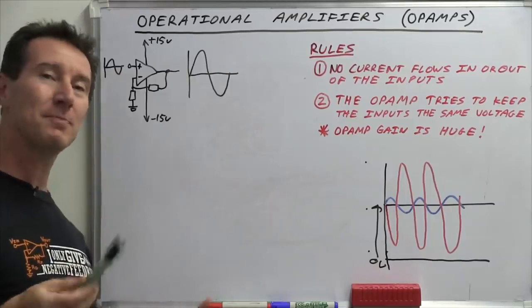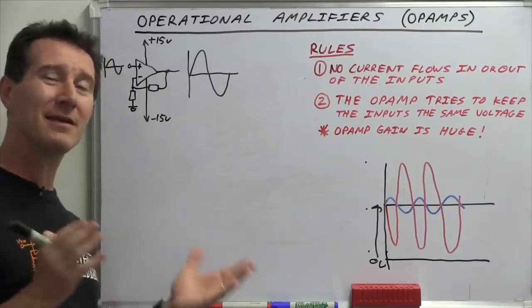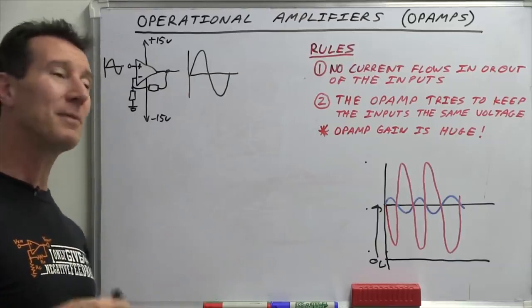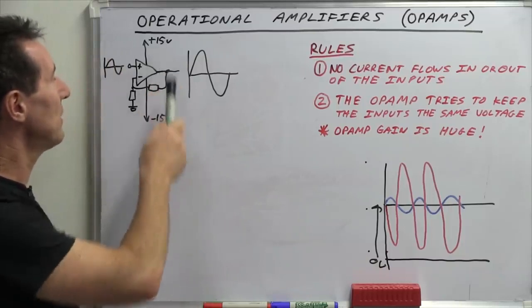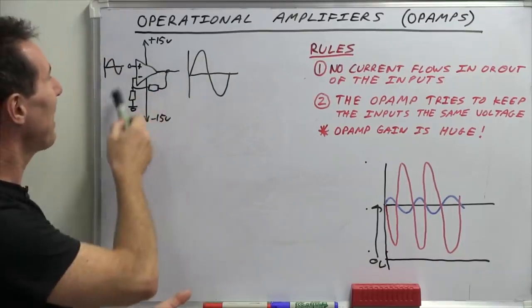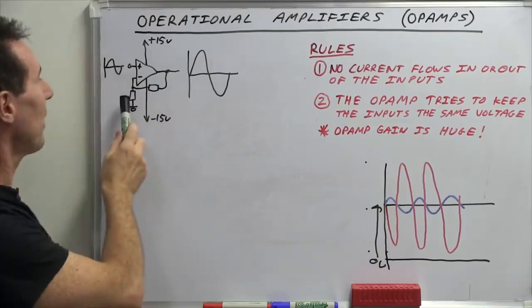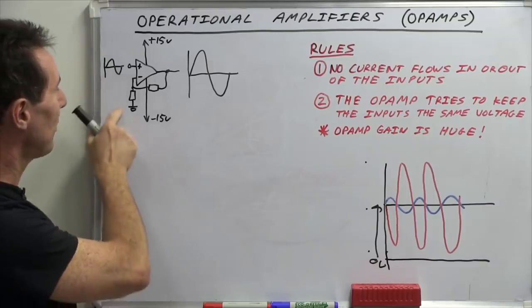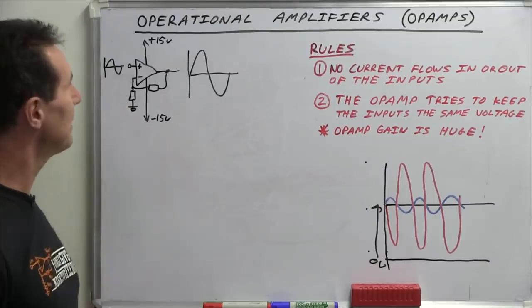Oops. So just back to this voltage rail thing briefly, because it is something that is rather confusing because there is no ground pin on an op-amp. There's only the positive and negative. So, well, where does your reference go? Well, the reference is part of the external circuit. In this case, back to our non-inverting amplifier configuration, here's our ground reference here, and then our positive and negative supply is here like this.